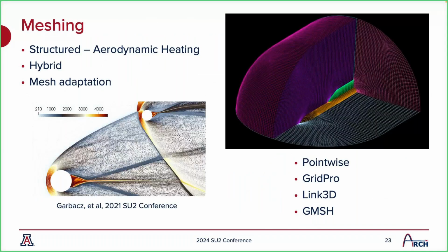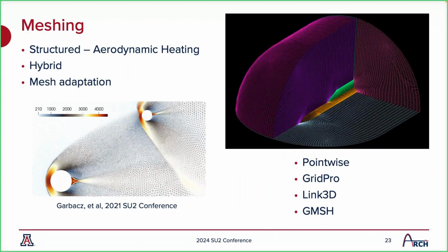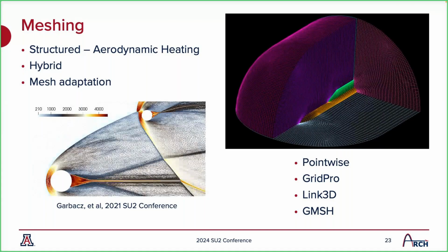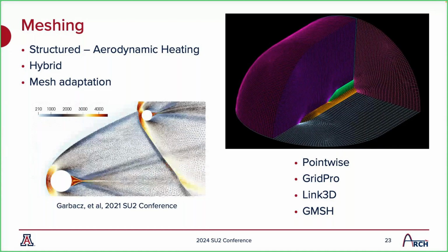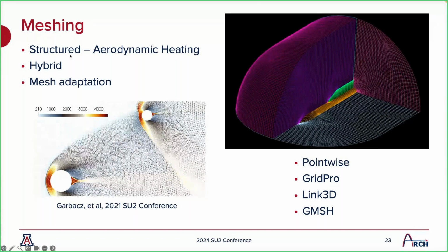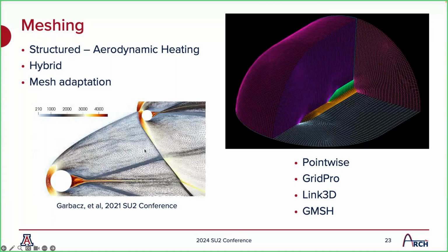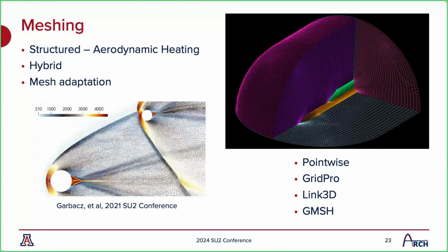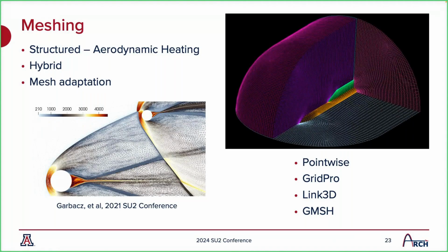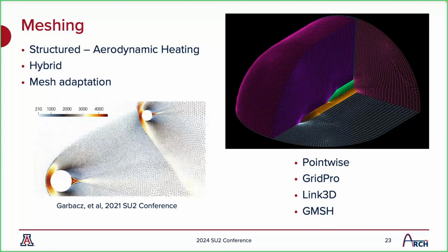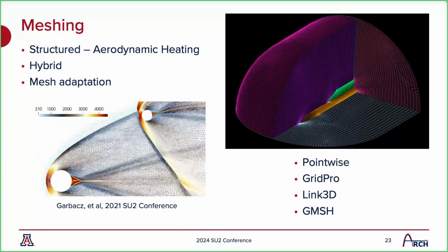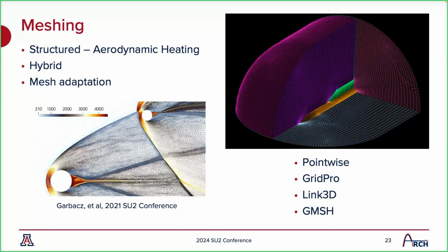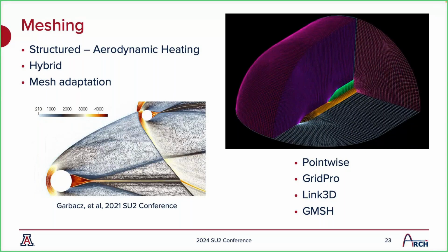And then meshing. We don't talk about meshing much in presentations, but in terms of man hours, this is where we definitely spend most of our man hours. Out of a motivation of looking at a lot of aerodynamic heating, we've gone down a lot of structured mesh paths, and we've also tried mesh adaptation, and we've seen some interesting results that I won't present here, but I hope in future SU2 conferences to break this multi-component presentation into a couple that we can go into more detail.